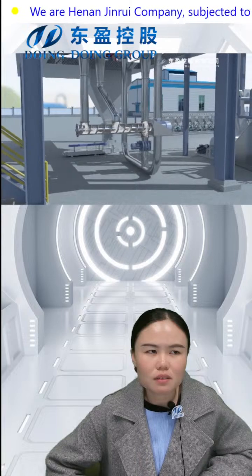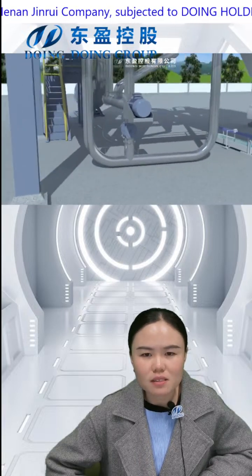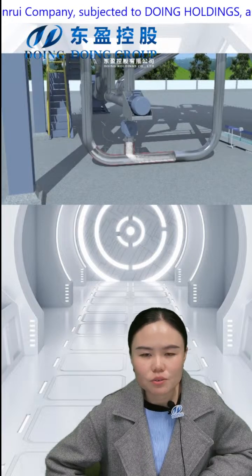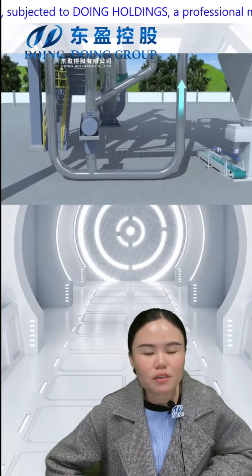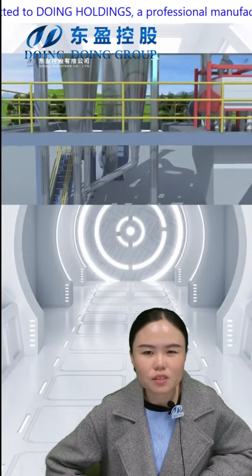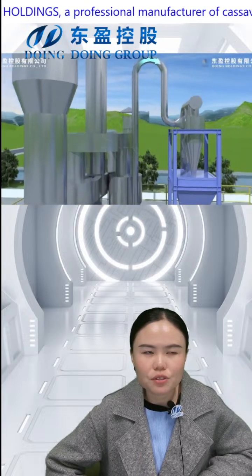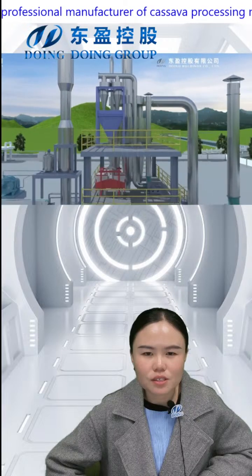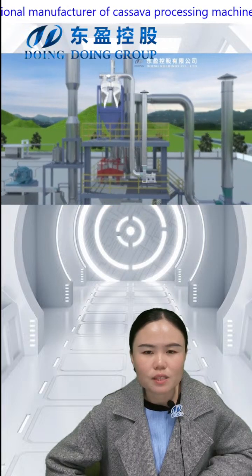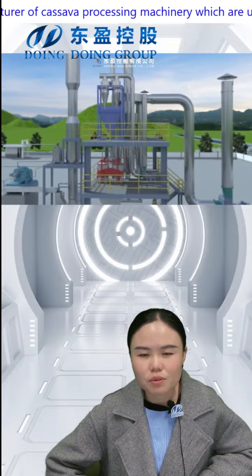And the moisture content of the final product can be adjusted according to the client's request. We have the interlock control system, the automatic control system, to control the temperature and the wet starch quantity, so that we can control the final output starch moisture content.